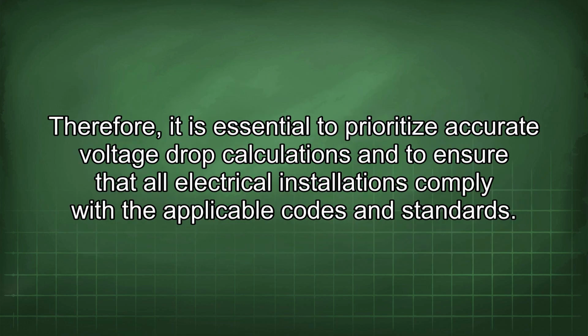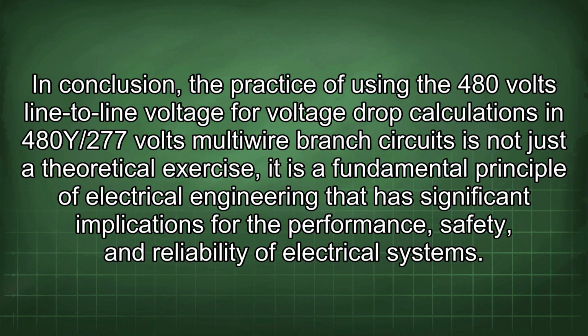Therefore, it is essential to prioritize accurate voltage drop calculations and to ensure that all electrical installations comply with the applicable codes and standards. In conclusion, the practice of using the 480 volts line-to-line voltage for voltage drop calculations in 480Y/277 volts multiwire branch circuits is not just a theoretical exercise, it is a fundamental principle of electrical engineering that has significant implications for the performance, safety, and reliability of electrical systems.